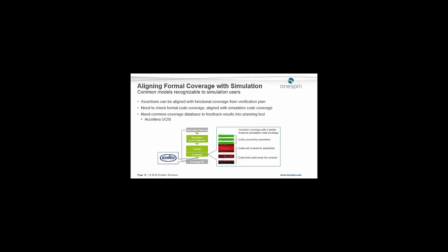But then, of course, after you've done this formal coverage, you want to be able to import this into the simulation coverage that you have. So you've got your verification plan, and you check the results that you're getting for your coverage from the simulation.